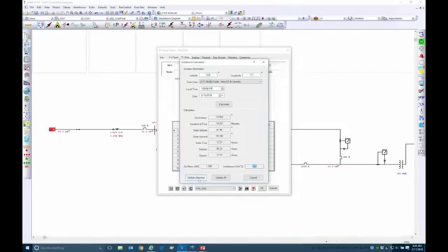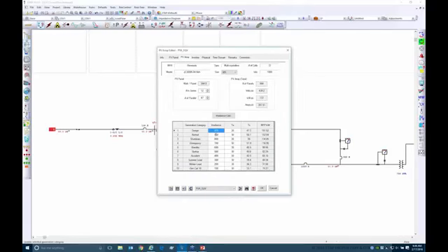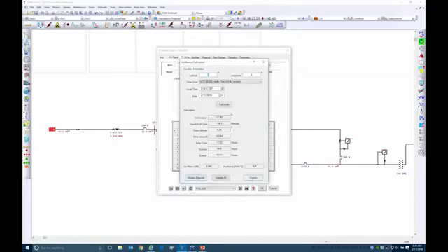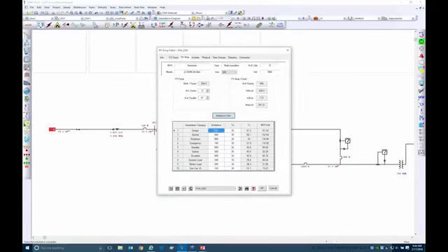And if I press on that update button right here, what you will see is that 875 gets plugged into one of my generation categories. There's another factor here that you have to plug in, which is the ambient temperature, because again, if you remember from those characteristic curves, the ambient temperature will affect the IV characteristics, and it'll affect the overall output of the panel.